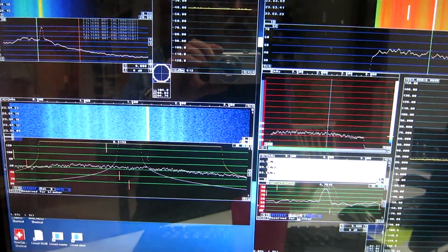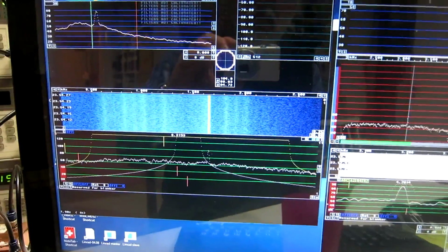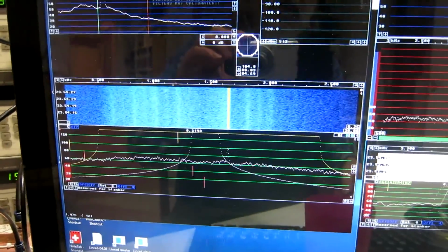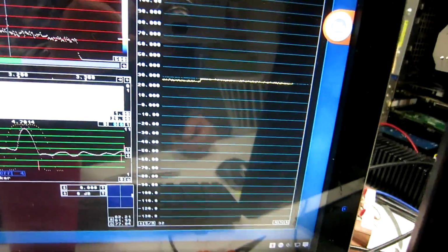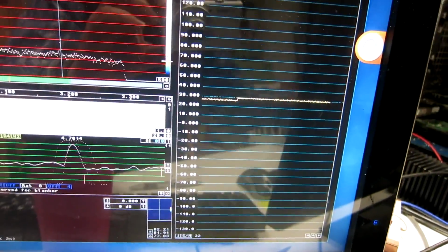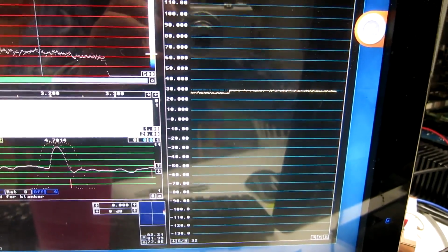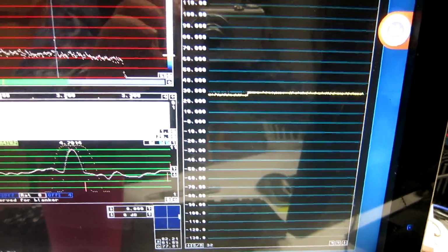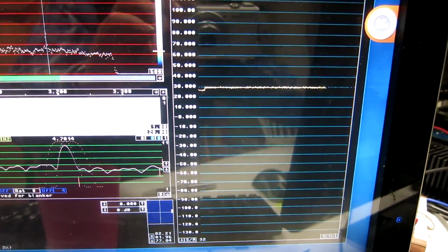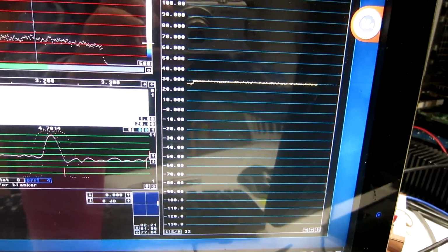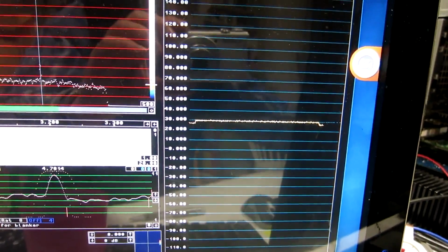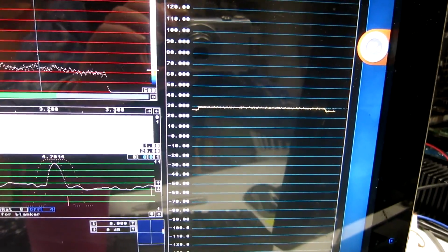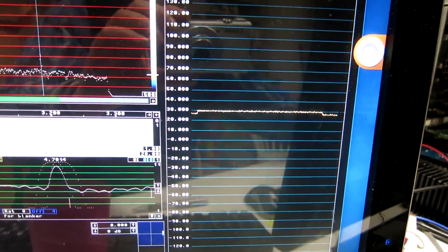I now set the 2 strong signals until I see something like a 3 dB loss in the signal-to-noise ratio in the Yaesu FT1000. This is maybe 3 dB, maybe a little less.